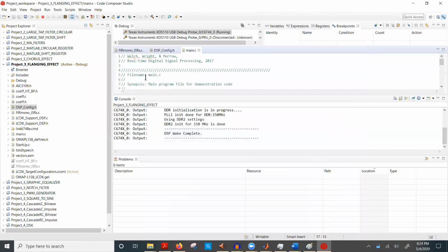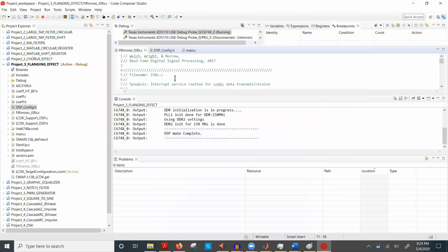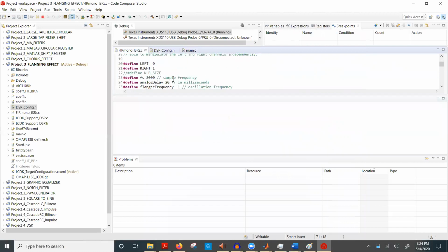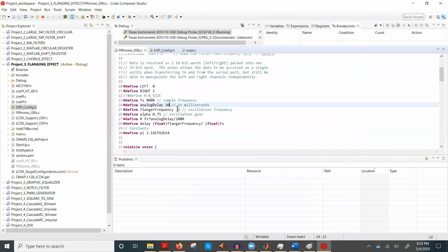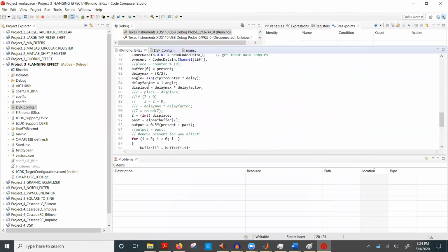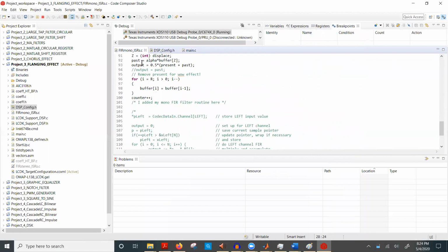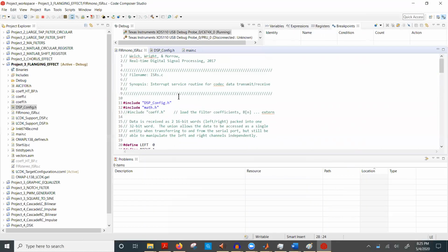So here we see that because I increased the delay slightly, there's more depth to the whining. So you can hear a more whining sound. The frequency is lower, so that's why it sounds slower. And I've included the present value stacked on top of the oscillation, so the original tone's right on top of it. And this is essentially all that there is to the flanger effect.